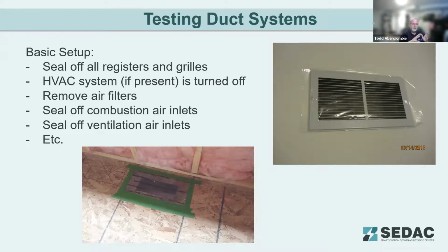Highly recommend, if you need to do this test, do it at rough-in stage before drywall is installed. If there's any issues, any additional duct sealing that needs to happen, it is much more difficult to do so after drywall. So often during rough-in stage, the duct tester will show up and do the test, sometimes before electrical is even powered to the facility or the building. And generally we bring our own power to power our fans. But by far that's the best time to get it done, because again, you can figure things out and get things passed quicker.